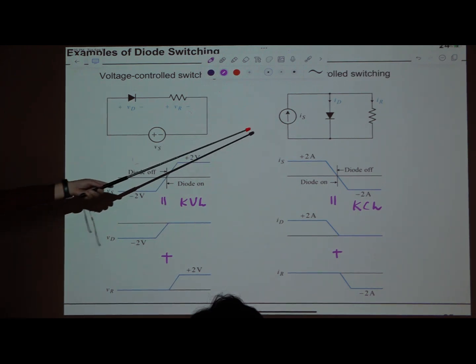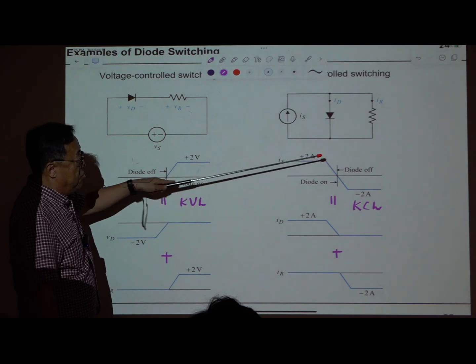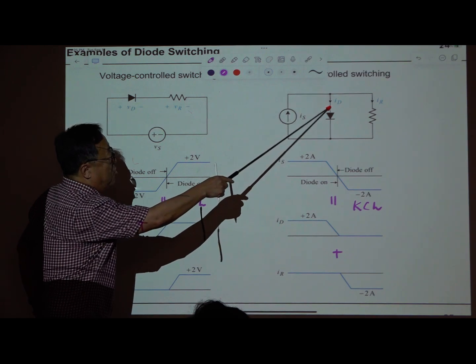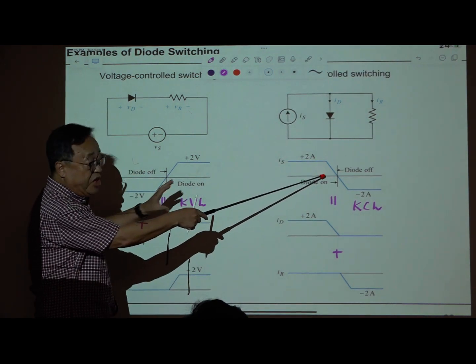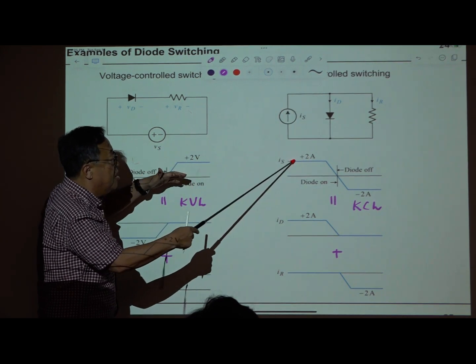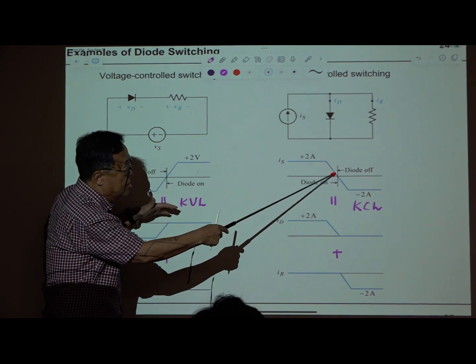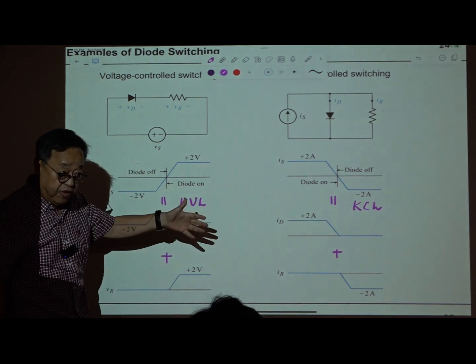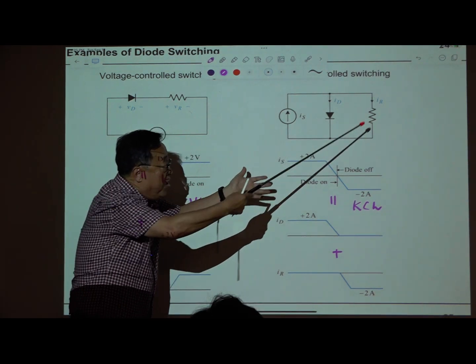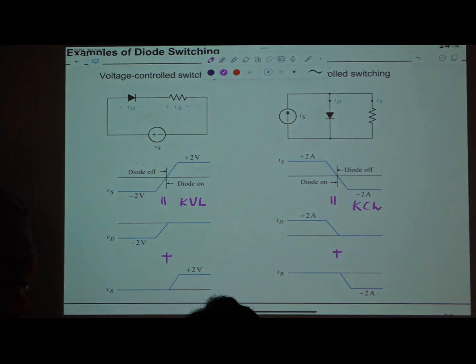Okay, so this happens a lot. In many applications, the current through the diode will be reduced for some reason due to the operation of other circuits. Then the current will be reduced like this, then the diode turns off. Okay, and this current should flow the other way around. It's called the freewheeling path. Okay, so we'll discuss the freewheeling path later.